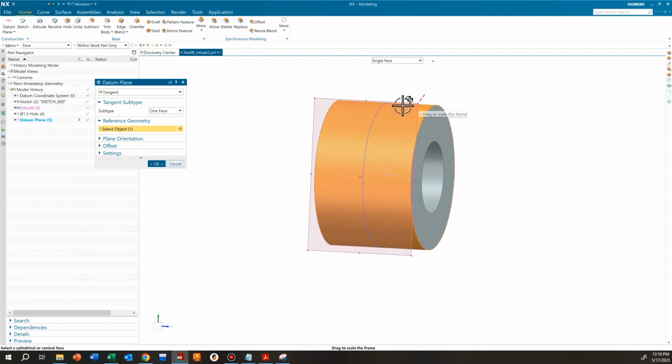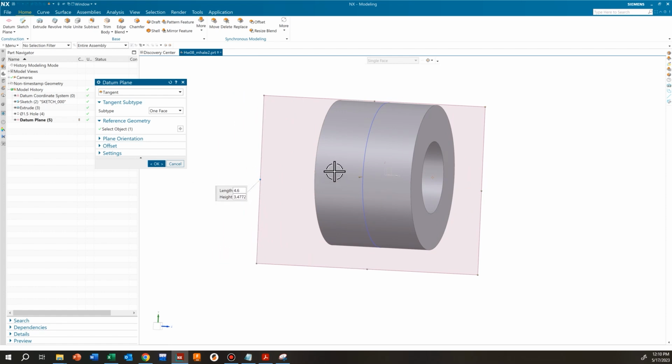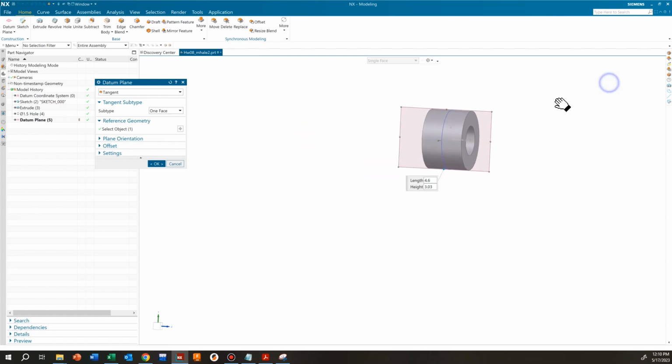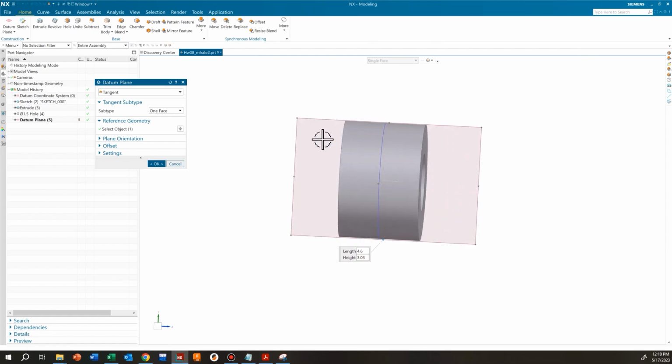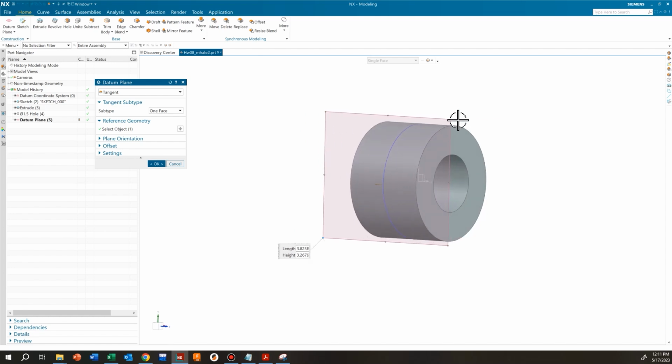Whenever we create a plane, you'll see these points or these dots on the edges. This is how we can resize the plane. But it is not defining the boundary of our sketch. So if we create a sketch that goes beyond this plane, that is okay. When we create a plane, the plane goes out to an infinite value. This plane never ends. Just because this purple area has a boundary does not mean that that's where the sketch boundary is at. So you can change this so that it's larger, smaller, whatever you want to do. But understand that that is not defining the size of the plane. It's just defining the size of the construction plane area that we see.